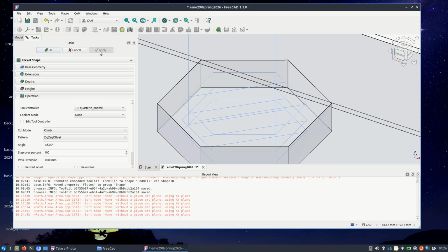Nothing wants to be cut, so sometimes it actually pushes some material to the side as it cuts. So if you do 0 overlap, when we come to cut this way, it's gonna push some material here. And when it comes to cut this way, the same material is gonna push it that way. So especially with wood, you're gonna have some fibers of the wood on the bottom, so it's not gonna be clean, right? So sandpaper.